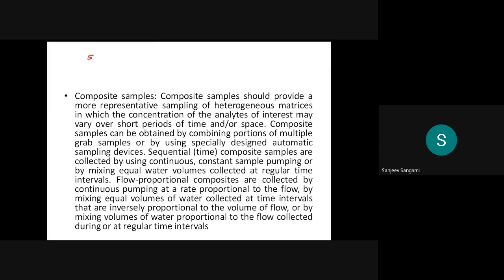We can take S1, S2, S3 as spots and collect all these at a time. So these are composite samples collected at a single time. Composite samples are collected by using continuous constant sampling pumping or by mixing equal volumes collected at regular time intervals. So this is what your composite sample is.